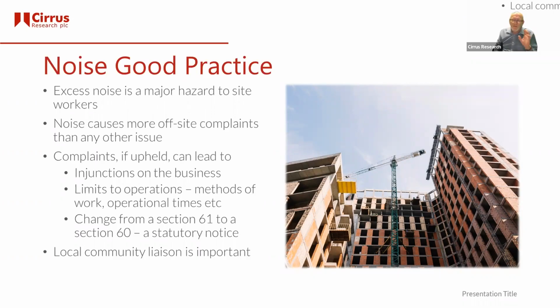Interestingly, noise causes more off-site complaints for a construction project than anything else, more than dust, more than the traffic, more than unsightly scaffolding, etc. It's noise that causes the most complaints. And because of that, if these complaints happen to be upheld, and most people would complain either directly to the site, but more commonly directly to the local environmental health team at the local council, this can lead to ultimately some injunctions on the business.